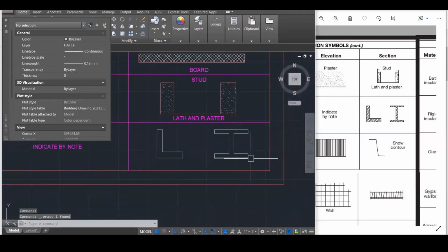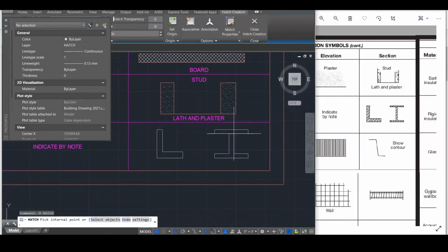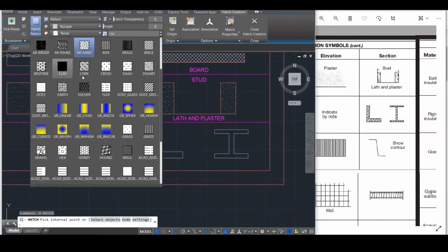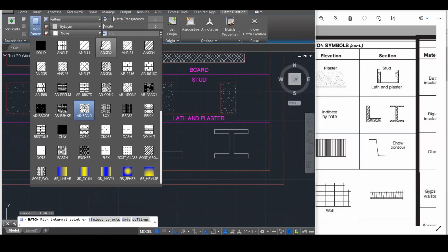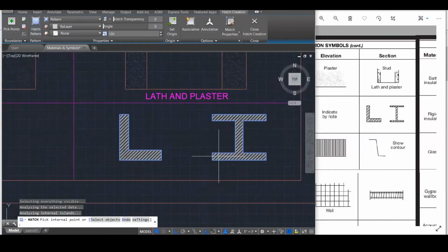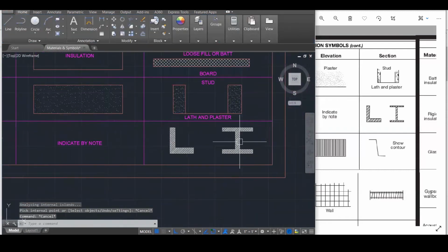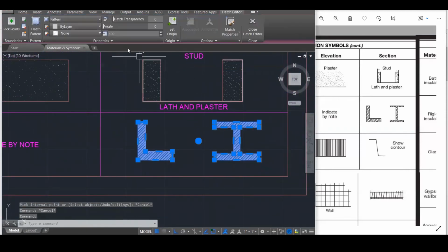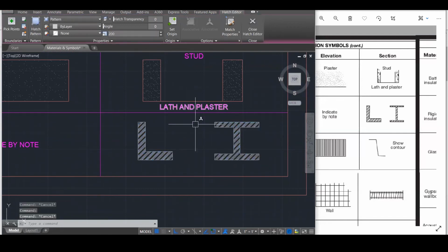Okay. Good. So now let's represent this by placing a hatch in here. So what hatch pattern can we place in here? Let me just close this off so I can see my hatch patterns. And we're going to need ANSI, or I think we can work with ANSI 34. Yeah, perfect. It goes in there, and that's the steel. Let me see, what scale is this? 100? Let's try 200. I think 200 is a little better.